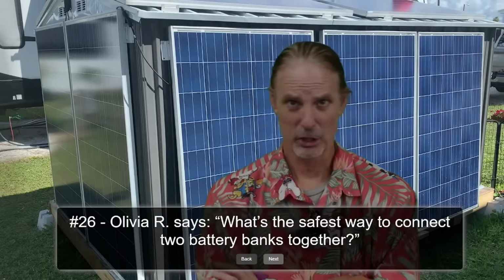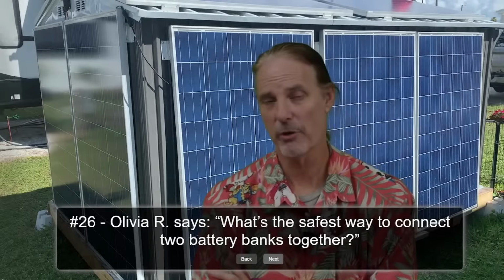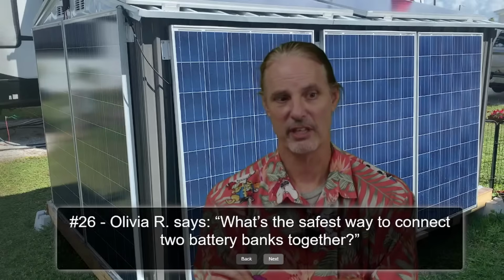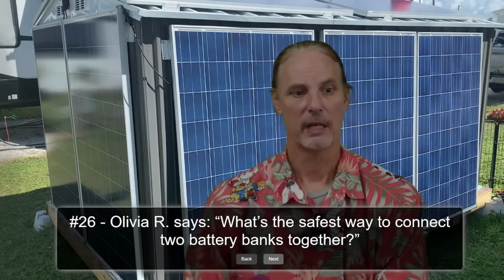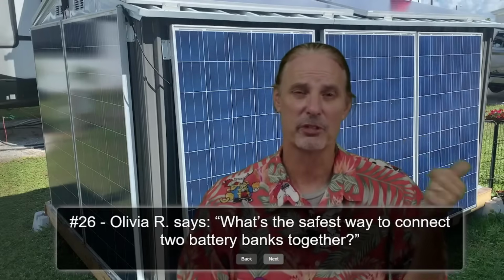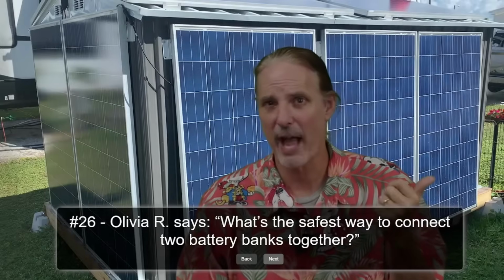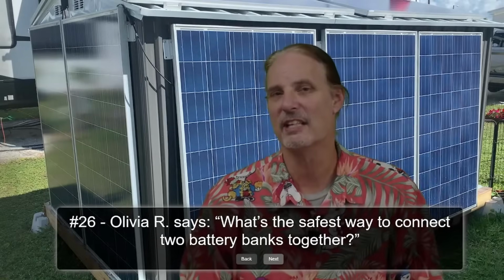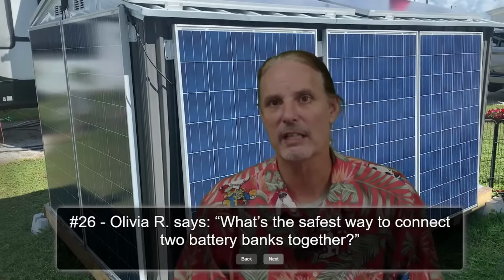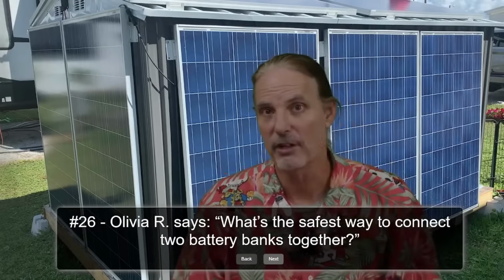Turn them on. Make sure that you don't see any big flows between batteries or big pulls. As long as they're all at the same voltage, or at least all fully charged, you won't see any, and that would be the safest way to do it. That's the short answer. There is a much more elaborated answer at the beginning of the live stream, so if you missed it, I suggest you go back and look at it there. But that's basically the idea: get the voltages very close to each other, and then you should be able to turn them on without any flow of power between the two batteries, and that would make it very safe for you to turn them all on.